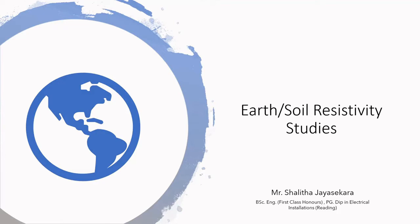And in today's lecture, we are going to learn about earth or soil resistivity studies, and as an electrical engineer, how you use this earth and soil resistivity knowledge in your day-to-day electrical applications. And in this lecture series, we are also going to talk about how to measure earth resistivity, what methods we are going to use, and how to select a proper place to drive your earth electrode into the ground. And we are also going to talk about various methods we are going to use to measure earth electrode resistance.